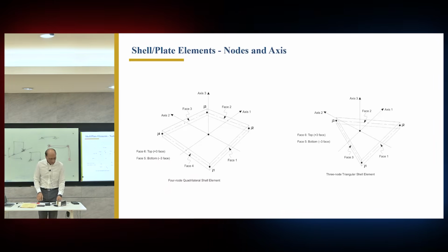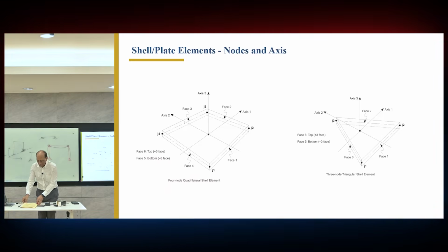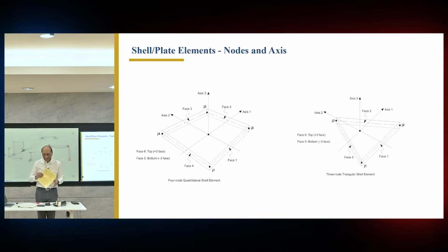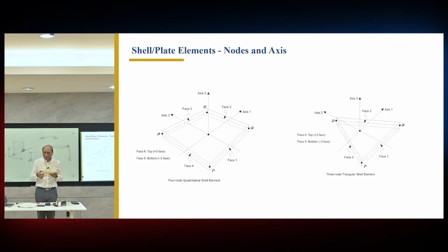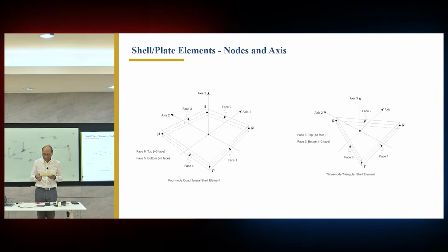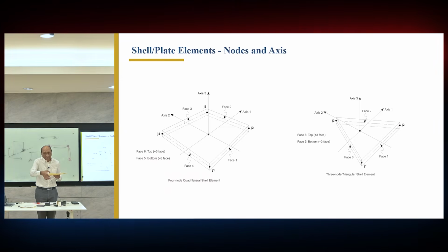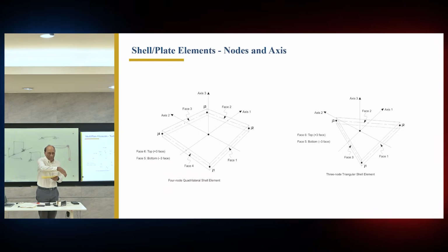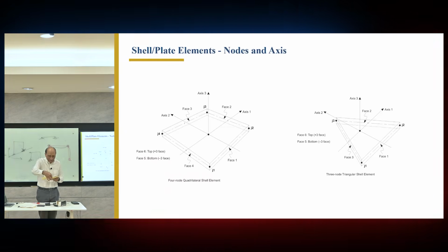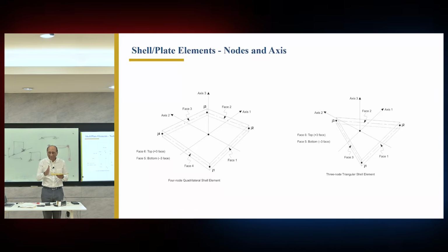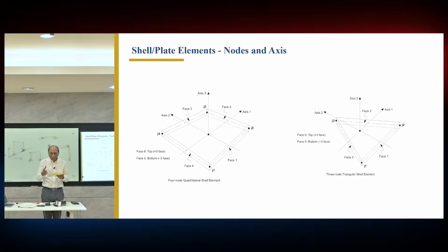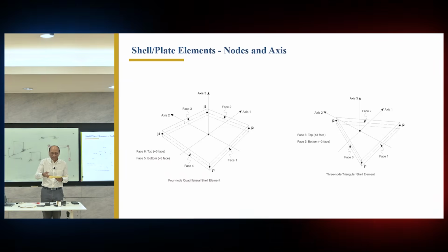The element is supposed to be like paper. It has the plane, it has no thickness as such. Thickness is a property. It's a two-dimensional element, not three. But when you put the thickness, then it will be like this. So the thickness is virtual. But that thickness becomes very important, because if you apply a load on the side, that face will take the load, so it is converted back into in-plane forces.